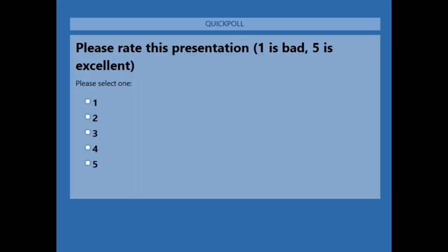Michael says, on motor control centers with molded case breakers and the arc reducing maintenance switch, we label line and load with and without the arc reducing maintenance switch. We do not label individual buckets. We go with worst case results with maximum and minimum short circuit data from the utility as well as their different switching modes. Okay, is there a question there?